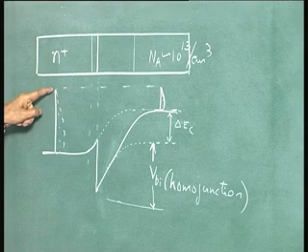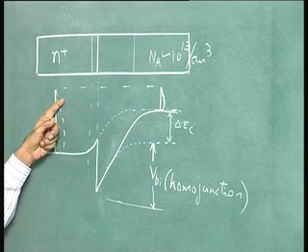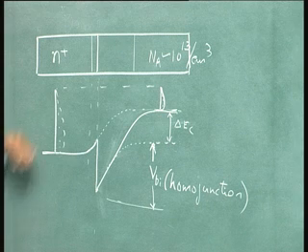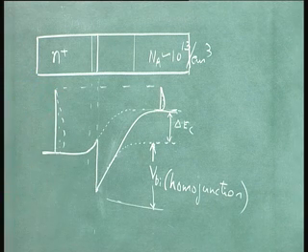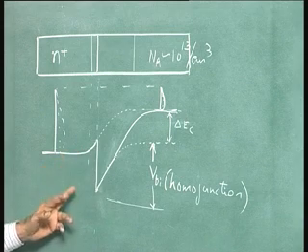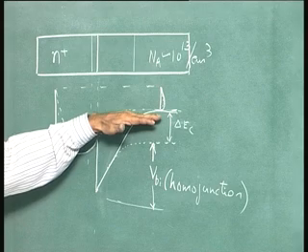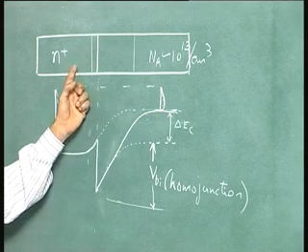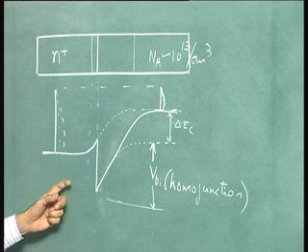Okay, it is like the war between the two. So, once these are at the same level, that is at the same maximum energy of electrons, no more net flow of carriers, current is 0, thermal equilibrium situation. So, this band edge keeps on rising here by transfer of electrons from here to here till this is raised up to that. That is the built-in potential.